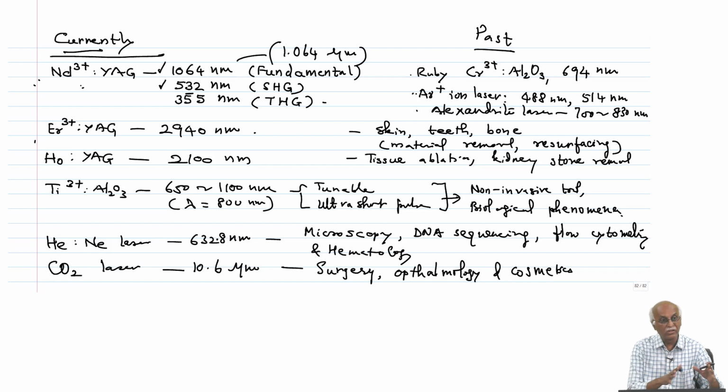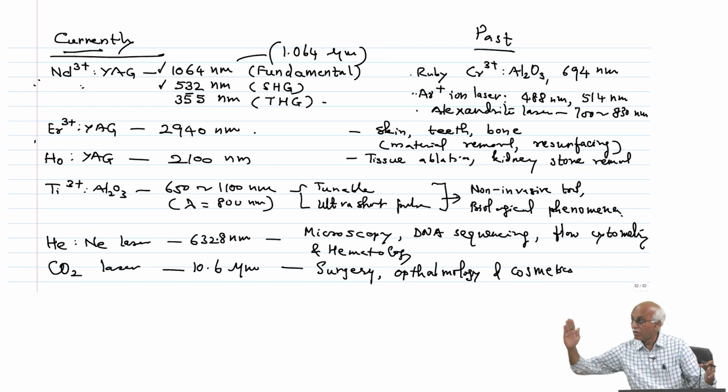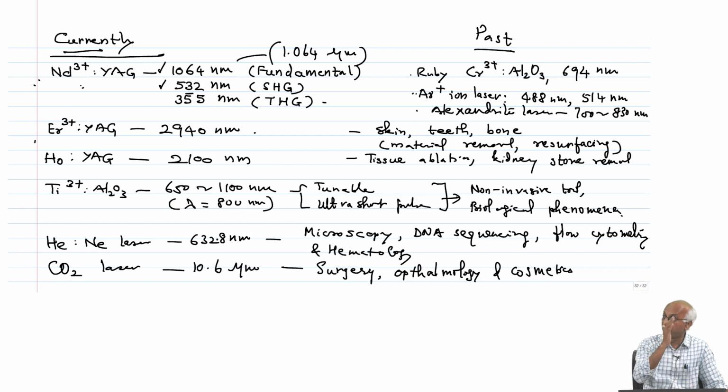Those are not laser sources, they are optical sources which can also provide a wavelength range for certain measurements, particularly in blood sample analysis, where you want to analyze various constituents in the blood, maybe glucose, hemoglobin, oxyhemoglobin, or other tissue aspects. Then we need widely tunable sources. In that case, it is not that we need a laser source; we can use a broadband source and a filter, tune the filter to different wavelengths, and extract the information.